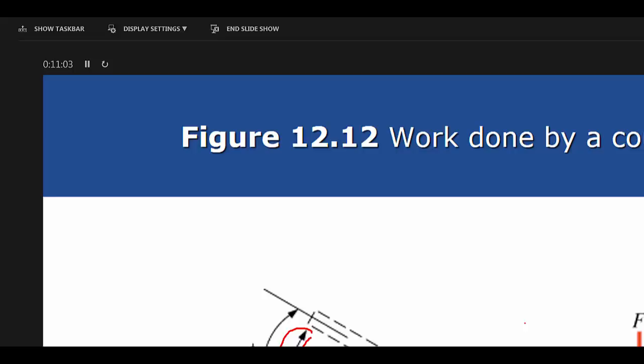Now, how much power am I going to be able to generate with that particular shaft and it not fail? That's what you're looking at there. 12.11. We've got a hollow steel shaft. Well, the only difference here is we're going to have to take the two diameters that we raised to the fourth power and subtract them out, right? So, and again, do that like it shows here.